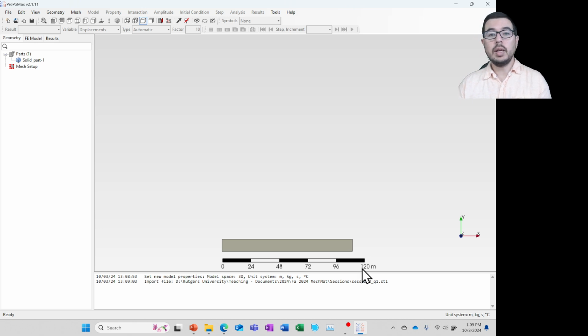Well, how long is this supposed to be? It's only supposed to be 11 centimeters long. So we have a scaling issue, and this is common when you use STLs, that one piece of software will export it with one set of units in mind, and then you open up another, and it doesn't match, because it's unitless in the STL format.